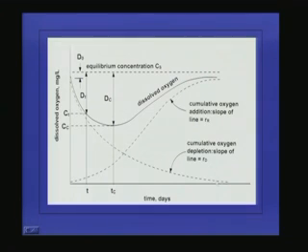So what is happening here? Here we are discharging some wastewater. So with respect to time, what will happen? Whatever organic matter is present in the wastewater will be utilized by the microorganisms. So with respect to time, the oxygen concentration will be decreasing. So we are taking the cumulative oxygen depletion. You will get a curve something like this, and finally it will become asymptotic or almost nil.